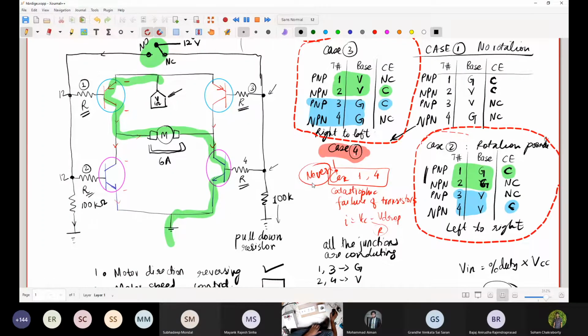I've put this in thermocol. The motor is coupled to a gearbox. The RPM of the motor is quite high, but there is a reduction gearbox so that you can have a larger output torque. It is used for many applications where you're looking for torque, not high speed.